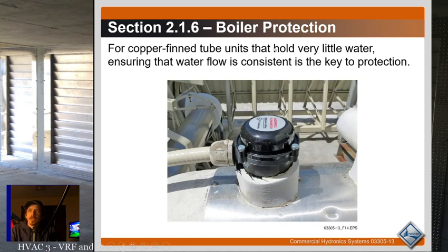Copper fin tube units that hold very little water. Ensuring that water flow is consistent is the key to protection. So making sure you have a flow switch.